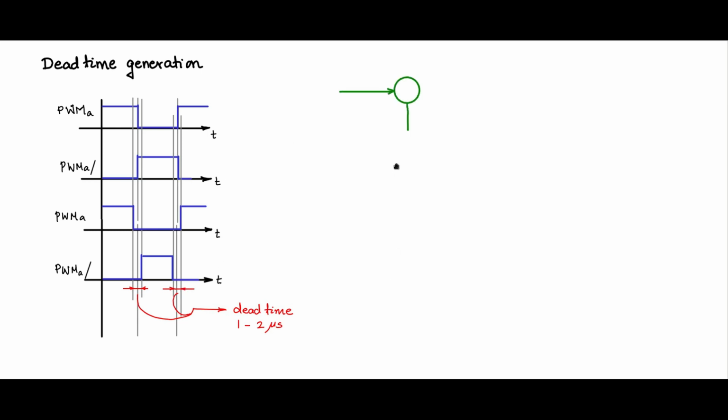So normally, if you take the PWM generation scheme, you have VM, the modulating signal, which is the low frequency sine wave, and VC, the carrier signal, which is the high frequency triangular carrier, compared in this fashion, plus and minus, and you get the PWM output. That PWMA is inverted and you get PWMA bar. So this is the normal way of generating, as we discussed. But let us now generate with a scheme which will give you this dead time generation inherently.